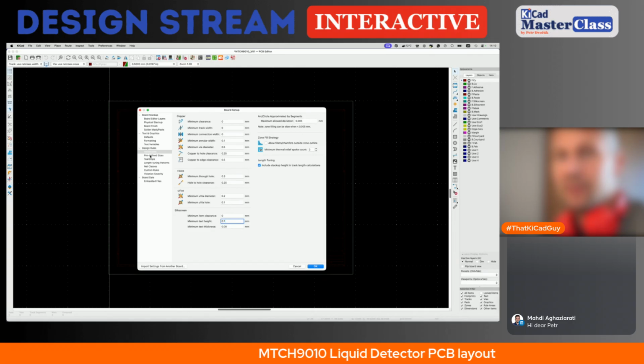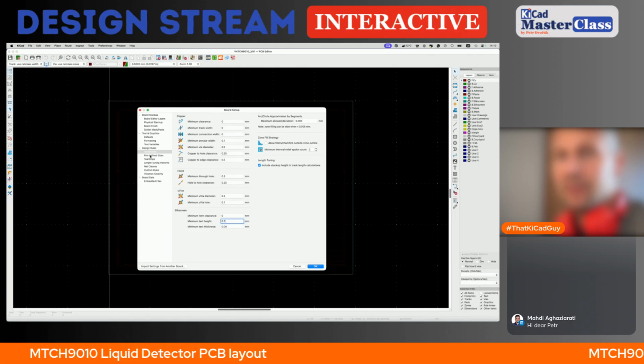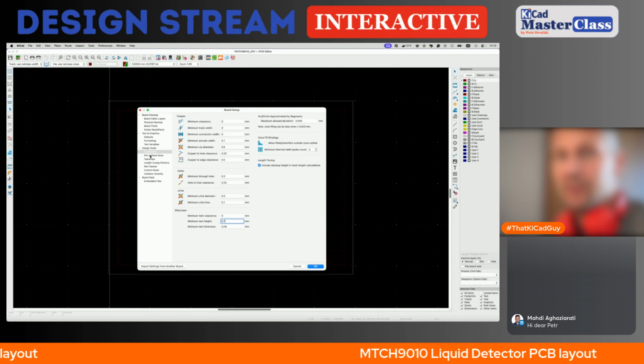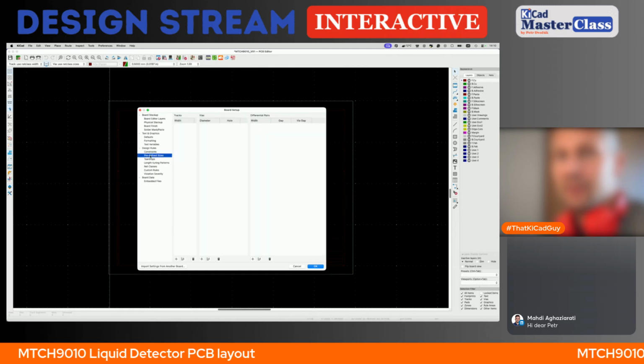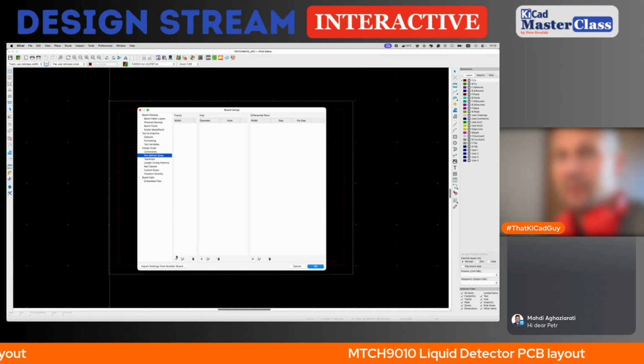This is something I am using. 0.8 is too big, and I tested many times in the past that 0.7 is the lowest text height that is easy to read and easy to place on the board when speaking of silkscreen design.